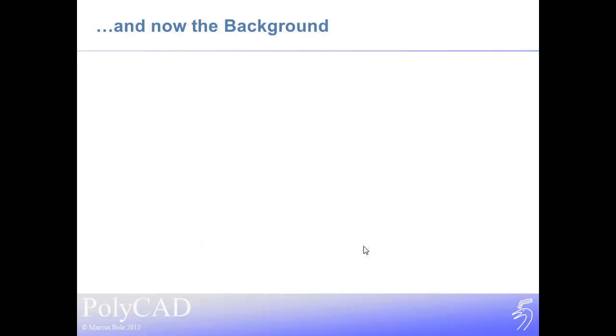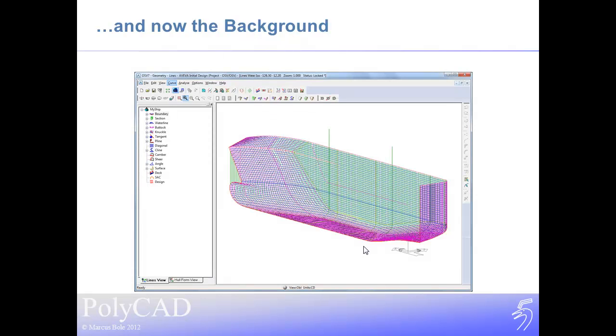So a little bit of background. I occasionally get to use a tool called Lines, developed by Aveva. Now this is quite an interesting tool where the whole surface definition is entirely based on curves. It is capable of generating a surface, but the surface generation process doesn't really happen until you've got a fair hull form, and it's done in a very automated process. So the user does not fair the surface directly using the surfaces unless they're getting to the final phases of production.